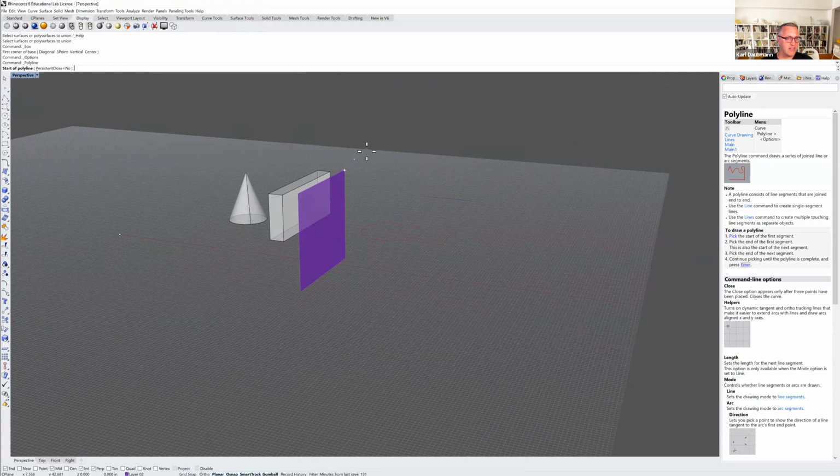And you can see as my mouse approaches something, probably the default, like probably you guys have end on. And so down here at the bottom, you can see end, near, point, mid, center, intersection, perpendicular. As you mouse over something, it will snap to them in a certain way. So end is really useful, or that's an intersection, or to that end and that intersection.